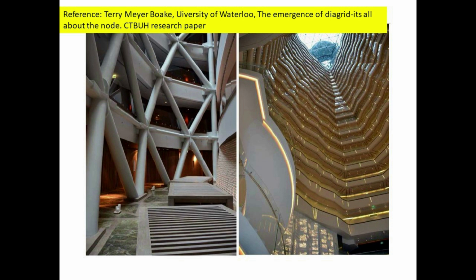The left figure shows the diagrid used to create central atrium spaces for the Capitol Gate Tower, and also for the Guangzhou IFC on the right figure. This type of structural system permits the floor system to span between the diagrid tubes.